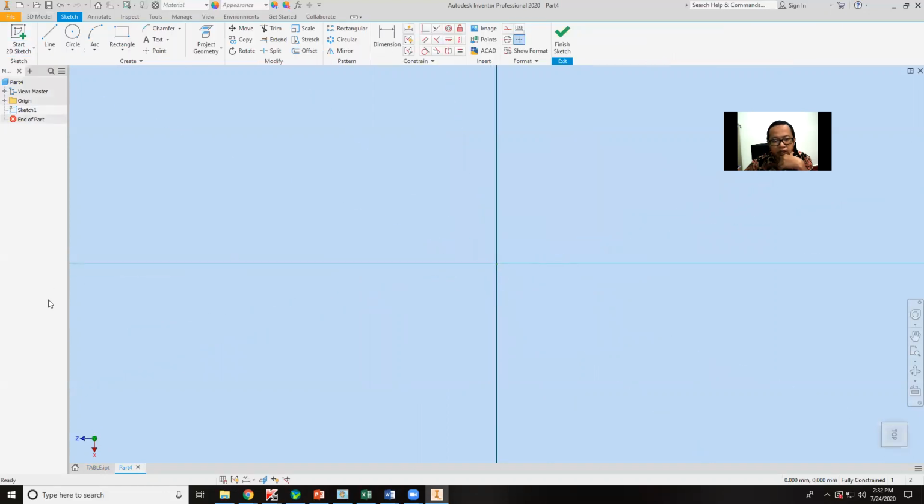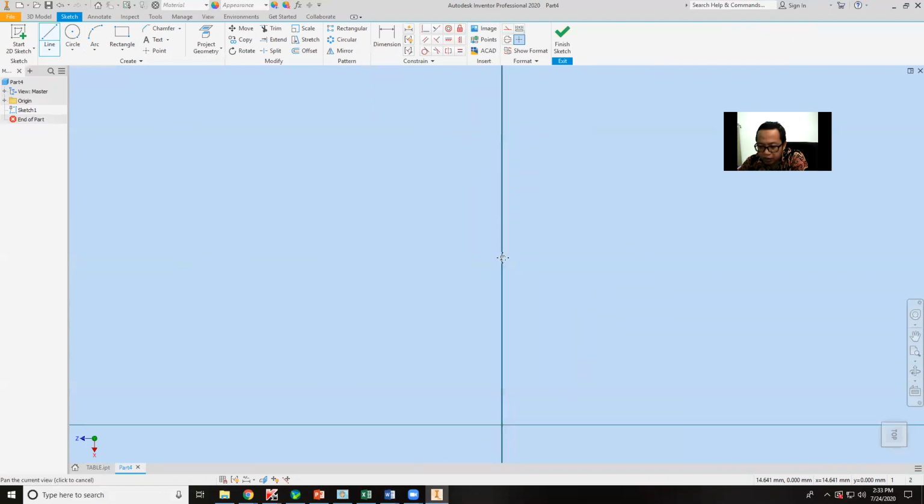All right. We try to make a revolve, right? Revolve is so important when we want to draw a product. I mean an object. Just click line for your first line, and you can click from the middle. You just take it like this. Press the middle of your mouse if you want to draw it, and you can click here.